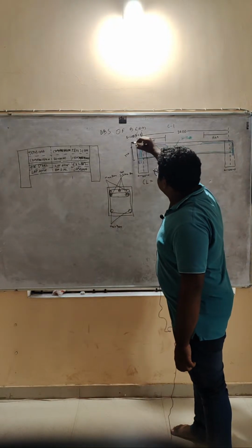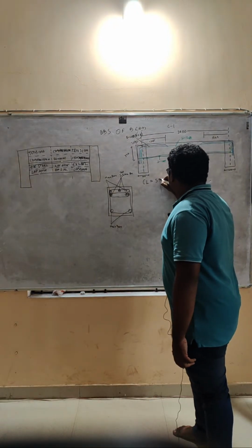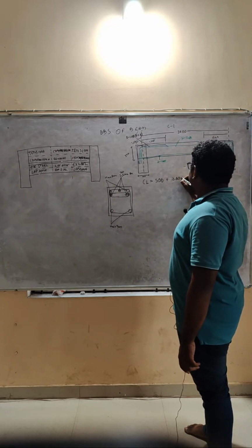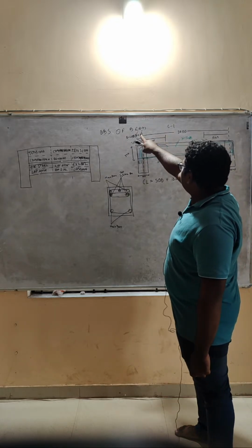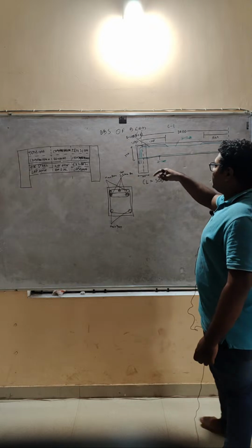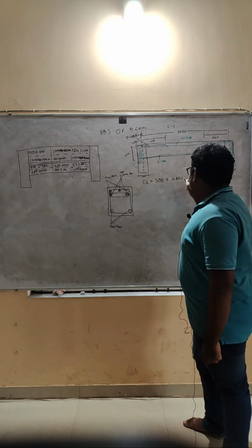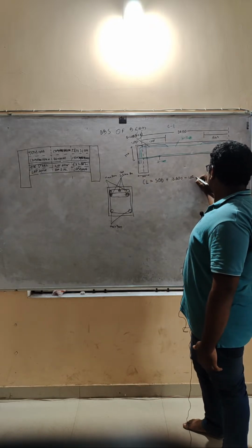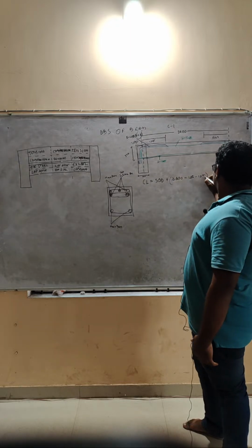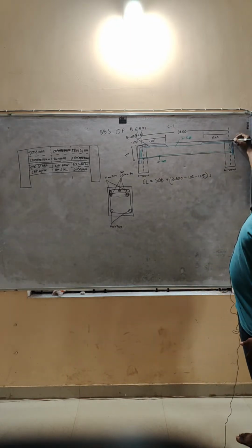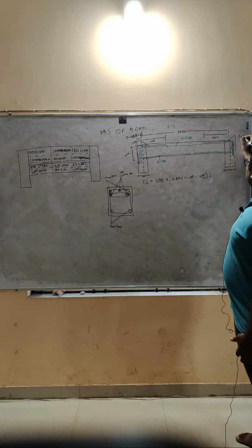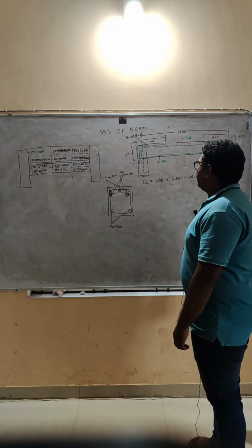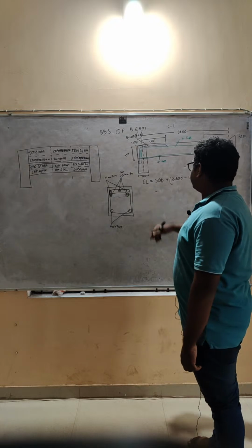50D, our LD, plus 3800. This 3800 is the length from center to center, which is the effective span. So we have to subtract, dividing the length by 2, plus another LD here, 50D. And we will deduct the bend reductions, which are 2 here, 2 90-degree bends.